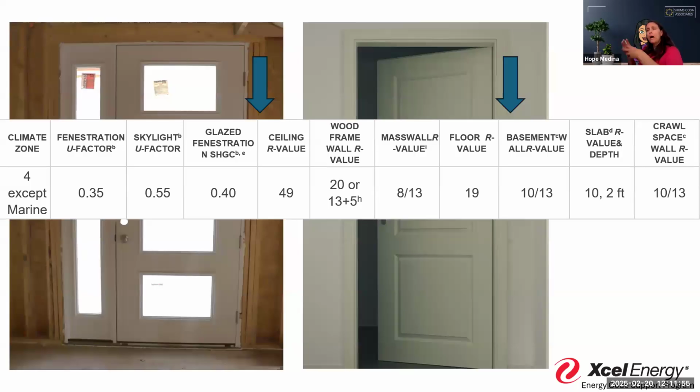It's a similar concept with that, but those doors could be, like in this one, it may or may not have some insulation between the two panels of metal. It might just be air, or it could be solid wood, or honeycombed, right? There's a lot of possibilities of what that U factor would be, but when you put the value into REScheck, it does the calculations to ensure that you are maintaining the integrity of that thermal envelope and that you're trading things off appropriately.